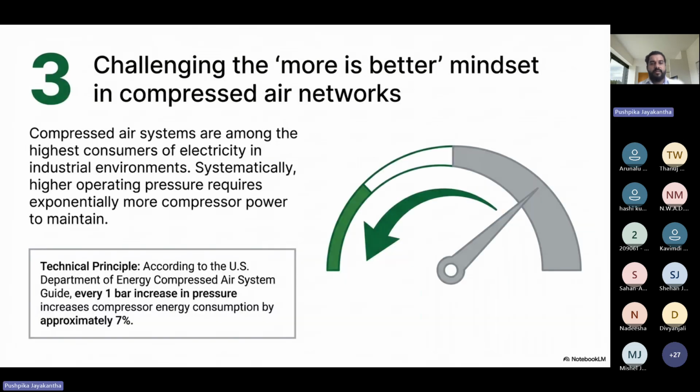So actually we discussed this compressor system in our case study also. These are widely used in manufacturing facilities and often considered the most energy intensive utility in these industries. The amount of electricity required to compress air depends heavily on the operating pressure of the compressor. High pressure requires more energy because the compressor must work harder to compress the air to a higher level.